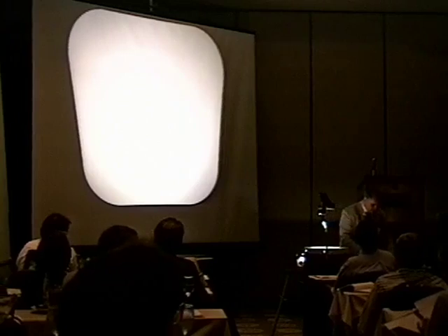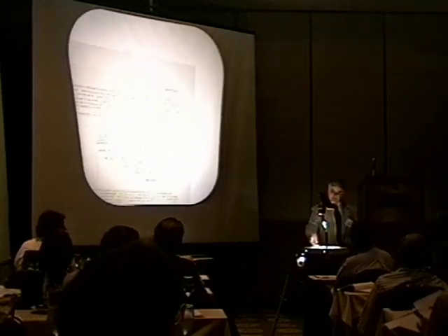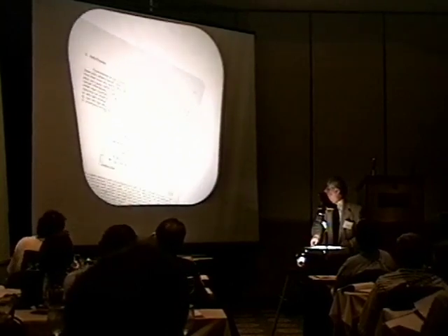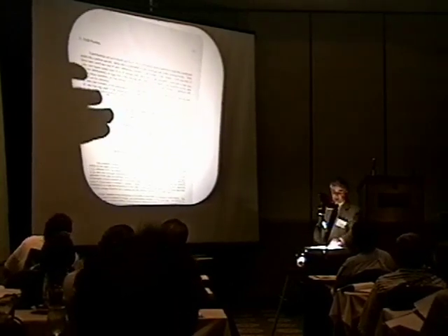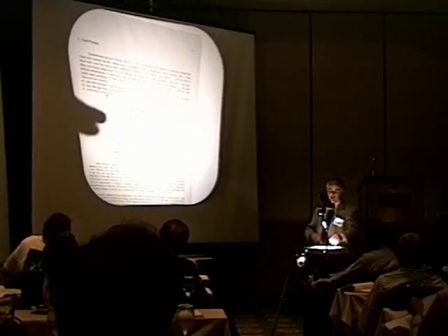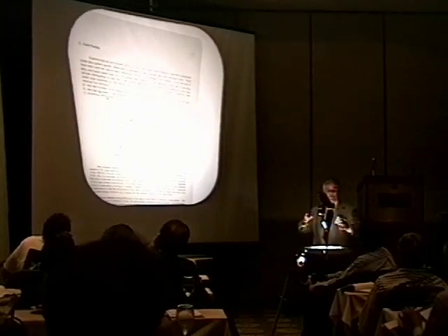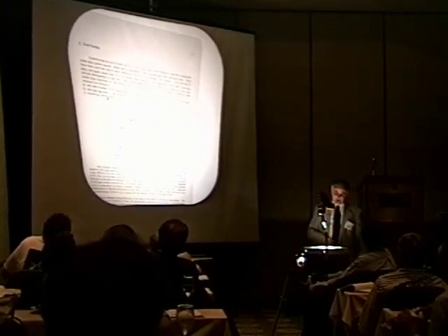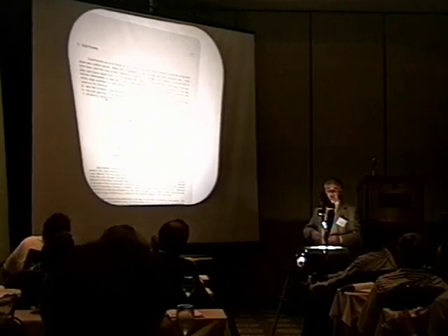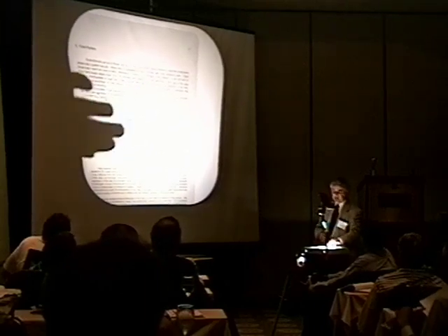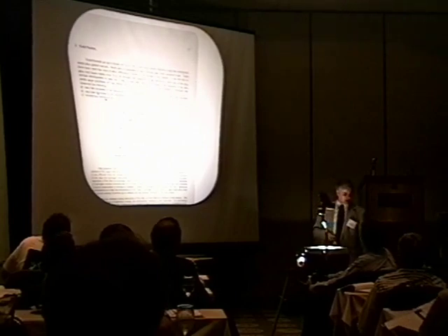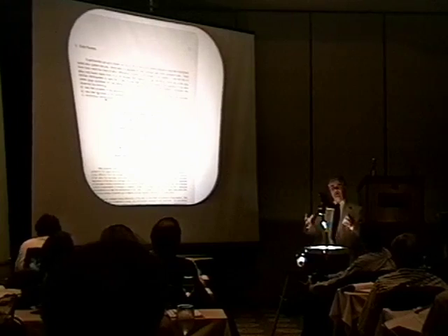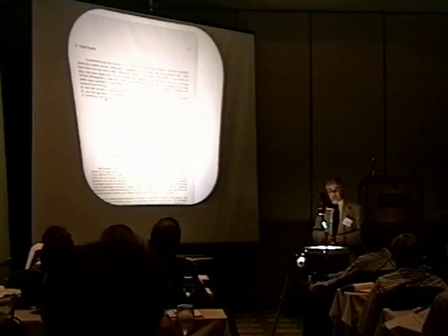In this case, what do we observe? First of all, we have to make a vacuum in this chamber to avoid any oxygen, during 2 hours. Then, during about 2 to 8 hours, we have to activate the material, because the material is covered by some oxide, and this oxide can be destroyed by high pressure, more than 8 atmospheres. And after destruction of this layer on the surface, the material starts to absorb hydrogen very well.